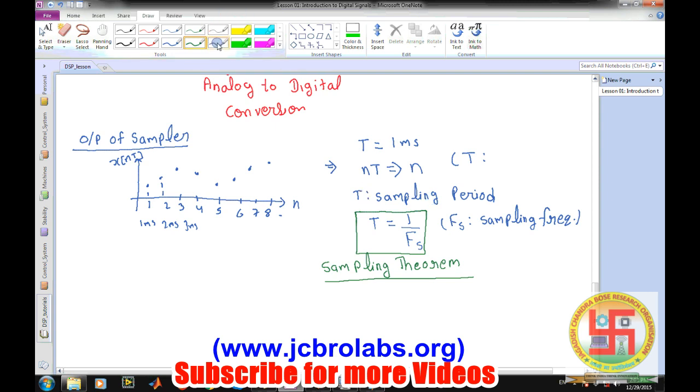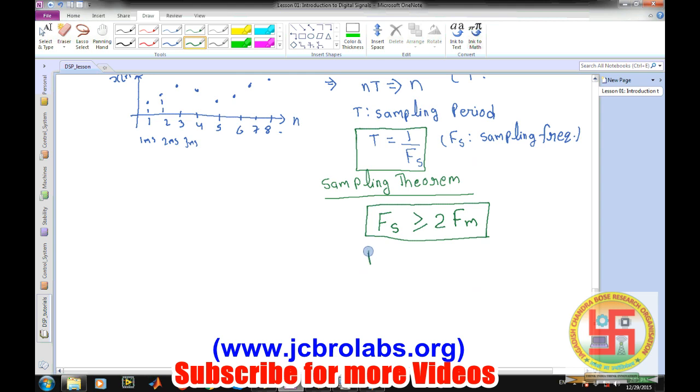So that is given by this sampling frequency. It says the sampling frequency f_s should be greater than or equal to at least twice that of the maximum frequency component present in the message signal, where f_m is the maximum frequency component in the message signal or any incoming signal.